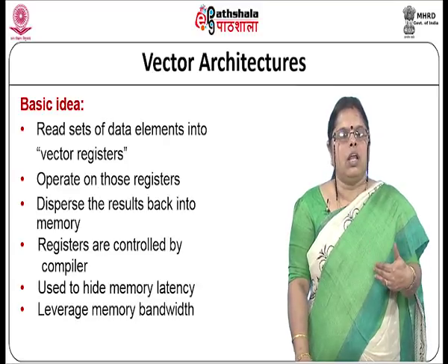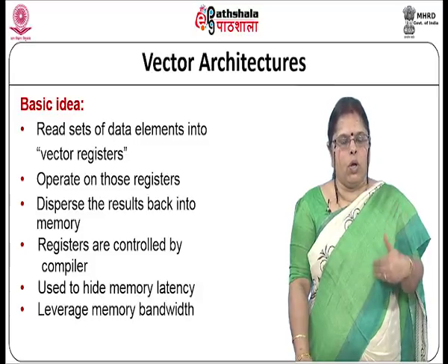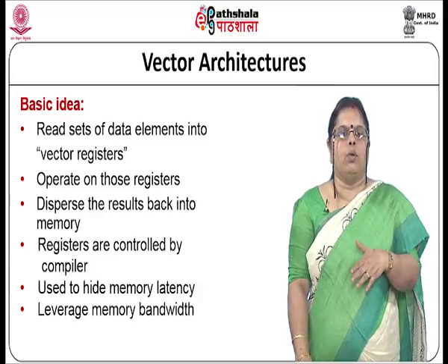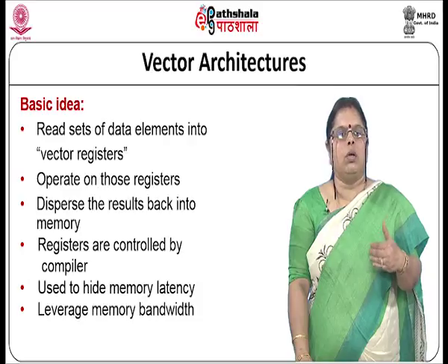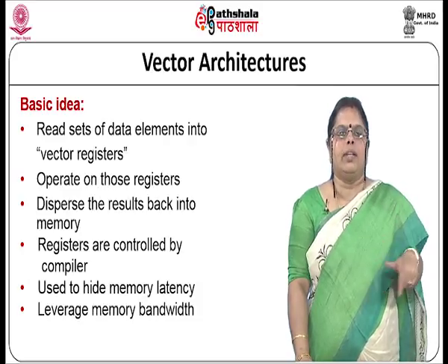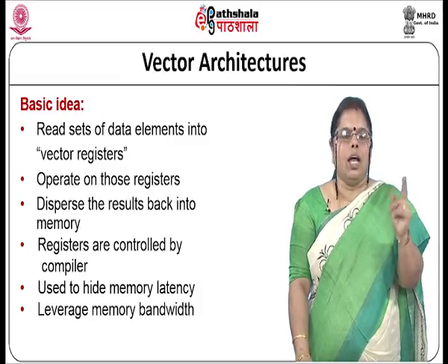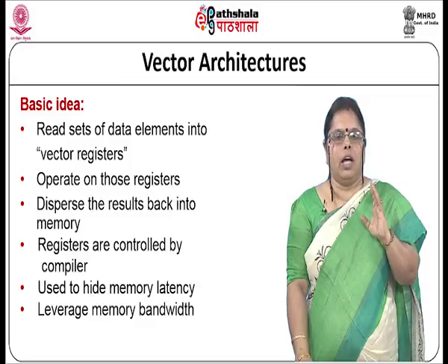In a conventional architecture, the first 2 elements are going to be loaded, they are going to be operated on, and they are going to be put back into memory. Your pointer gets incremented, you get the next set of elements, and you do them. So, basically it is executed in a loop. That is how a conventional architecture handles a vector addition.